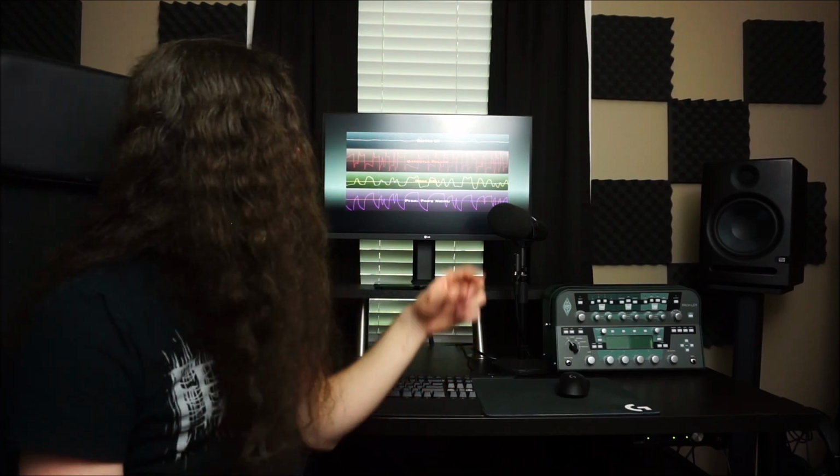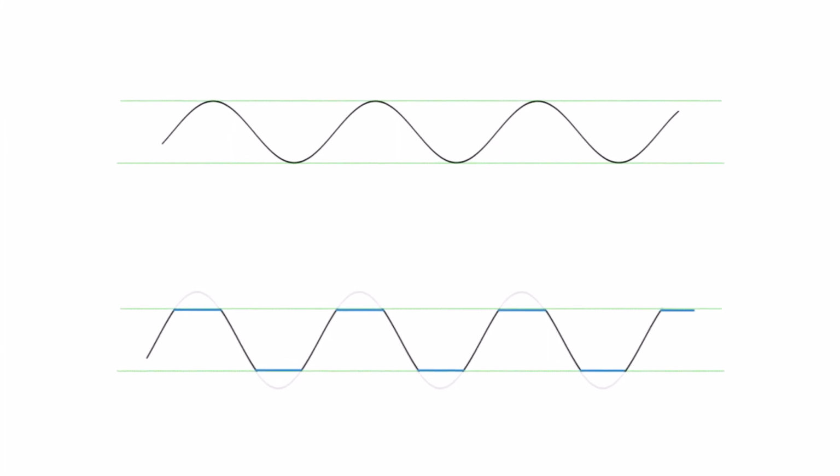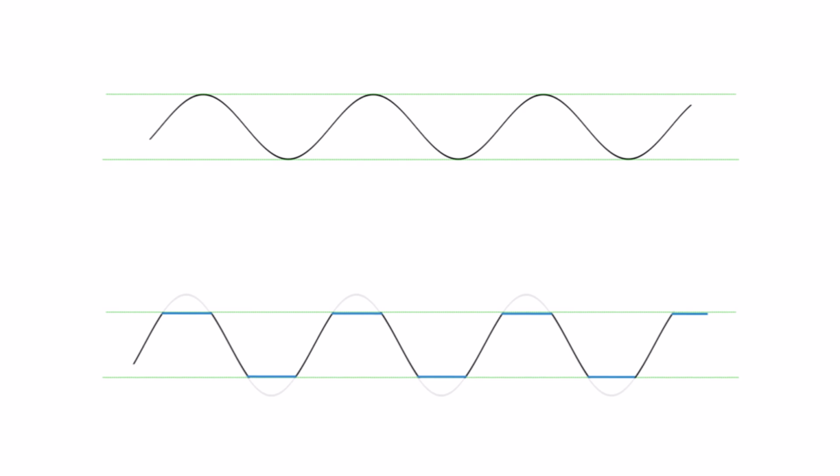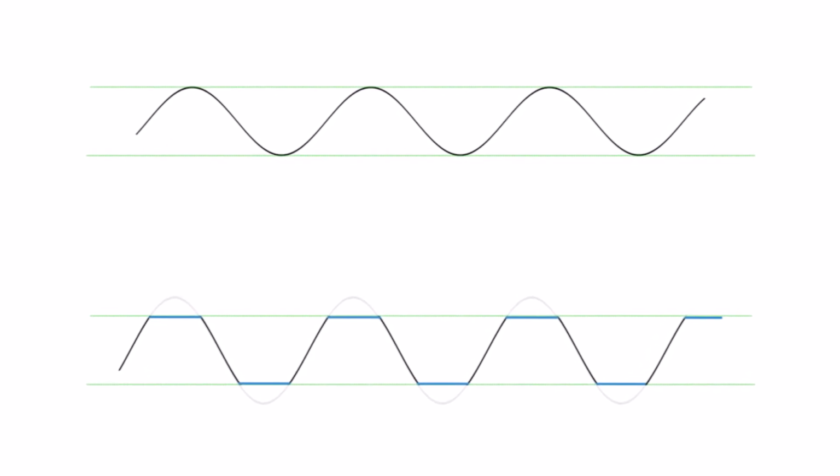Because as you might be able to see even from this visualization of pedals and a guitar preamplifier, the more you clip a signal, the more that the signal spends time at the maximum threshold. So, if we have a threshold of 1 volt and we've got a sinusoidal wave that has an amplitude of 1 volt, but we double the gain, and now we're clipping for a lot of that signal, what's actually happened is the signal is louder. The signal may never actually trip that 1 volt threshold, but it spends more time there, and through the persistence of that signal, we hear it as being louder, which has thereby decreased the dynamic range of that signal.